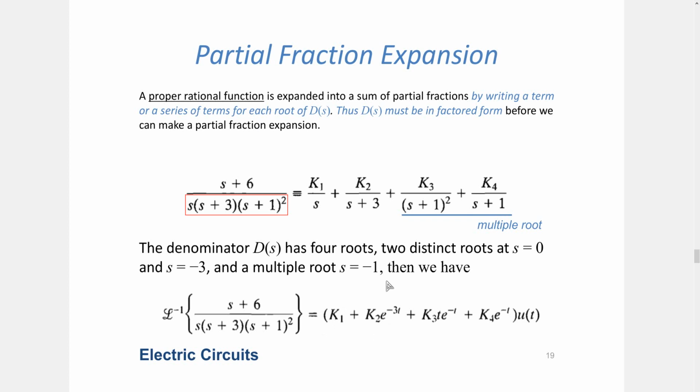But eventually what we have done is we go into the frequency domain, we compute something, and then we decompose it, we factorize it. And then for each term, we compute the time domain equivalent by taking the inverse Laplace transform. So it's essential to have an understanding of the time domain function and the frequency domain transform. If you see the transform, you can estimate the time domain function, or if you have the time domain function, you can transform it into the frequency domain to do the solving.